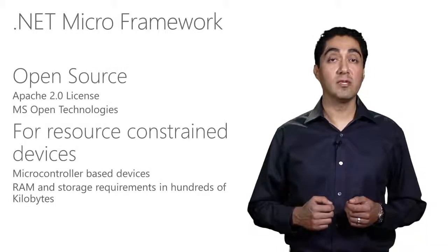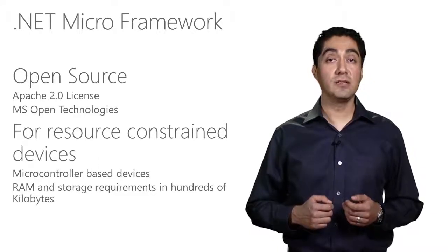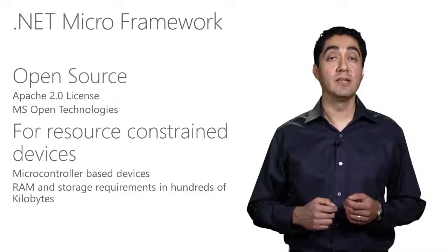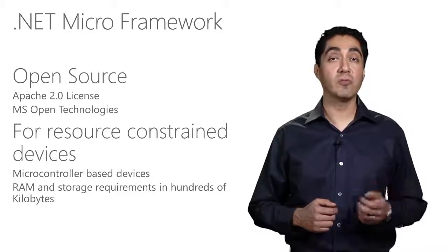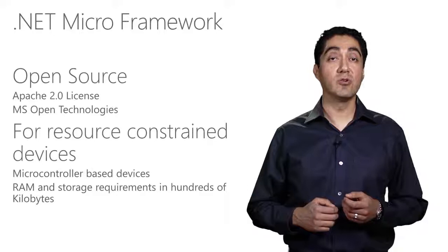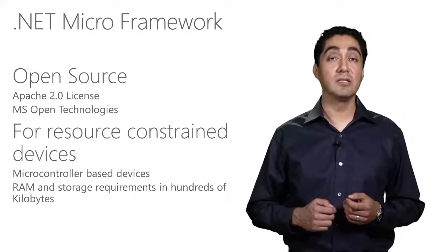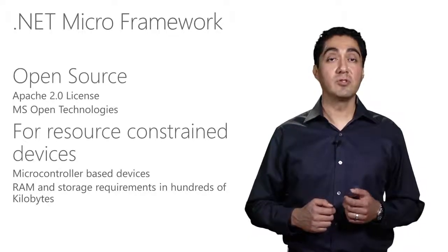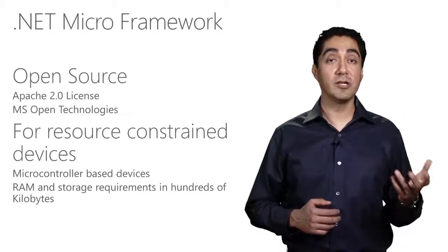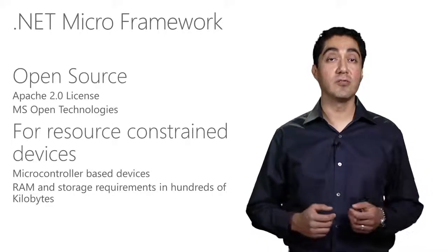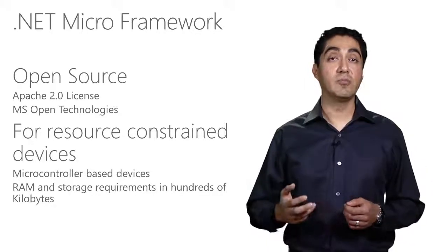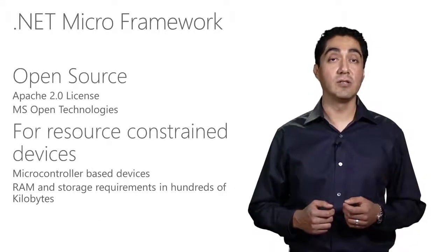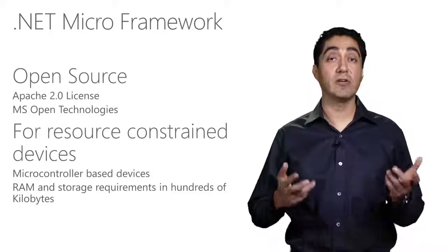The .NET Microframework is an open-source platform that enables you to write and manage C# applications using Visual Studio for resource-constrained embedded devices. The Microframework is open-sourced by Microsoft Open Technologies and licensed under the Apache 2.0 license. Microframework can be used to write applications on resource-constrained devices running on a microcontroller with just a few hundred kilobytes of RAM and storage. The typical Microframework device has a 32-bit processor with or without a memory management unit and could have as little as 64K of RAM.